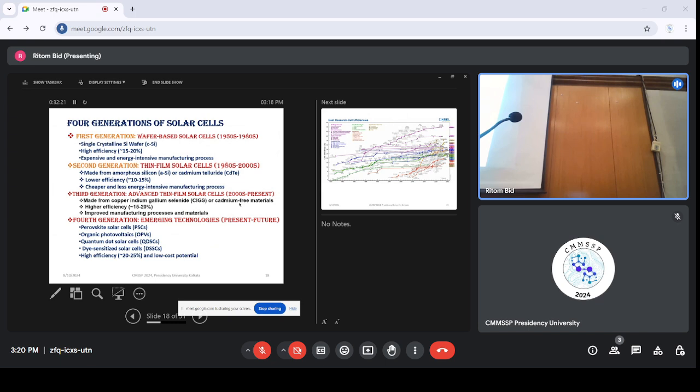That we will talk about today, that is CZTS. In CZTS, basically, the indium and gallium are replaced by zinc and tin. So they are earth abundant, and at the same time, they are not toxic for the environment. That's the issue. So these are the emerging technologies, that means these are different ideas of getting efficient power from the incident light.